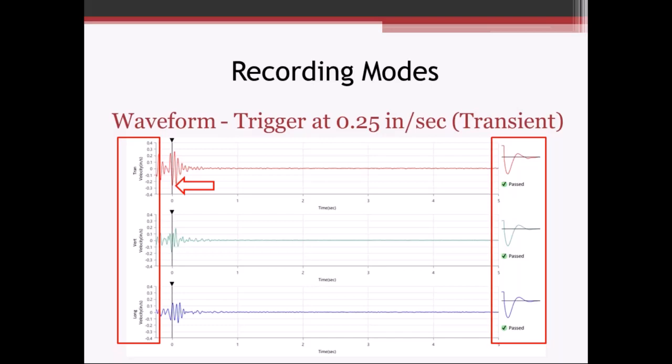So the magnet goes up, and when it releases that voltage, we want to see that magnet drop back down and vibrate back to a steady state condition. So that's what this waveform is here. Here's the voltage, it releases it, that magnet just travels back and settles back down. And that's done at all three of those geophones inside.